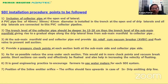So the installation procedure that is generally followed by the farmers: you have to have a collector pipe at the end of the pipe. Typically, it could be a PVC or HDPE line of 40 or 50 millimeters. Then the trench level of the collector pipe should be deeper than that of the other trenches, because we want the water, and any debris that is collected, to get flushed out. So you will have to keep it at a slightly lower level so that all the debris gets collected at the bottom. Then, as I already emphasized, the air release cum vacuum breaker valves at the required locations.